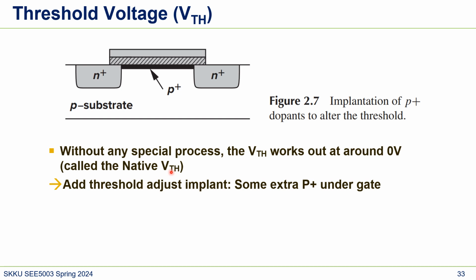There is a device type, in fact, when we design circuits, there are multiple types of NMOS. One type of NMOS is the native MOSFET. That means they don't have any VTH. I mean, their VTH is zero, which means they're always turned on. We use it sometimes. I have also used it for some certain purposes.